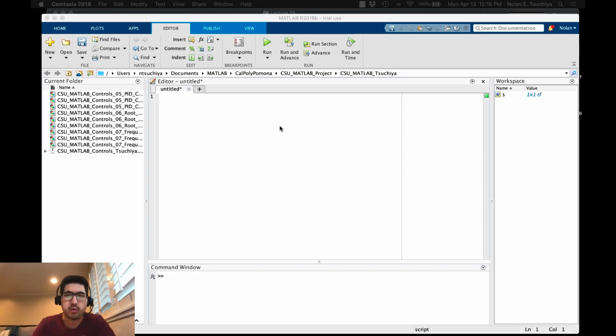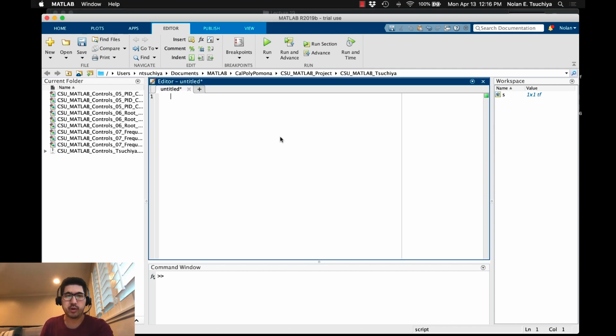So what we can actually do is verify some of the things that we just computed analytically, numerically. We can allow MATLAB to do a little bit of filtering for us so we can see what the output looks like, and hopefully it'll agree with the analytical computations that we just performed. In MATLAB we can always define our Laplace variable, which allows us to write transfer functions in terms of that variable s. The transfer function we were dealing with was pretty simple. It was just 1 over s plus 1.